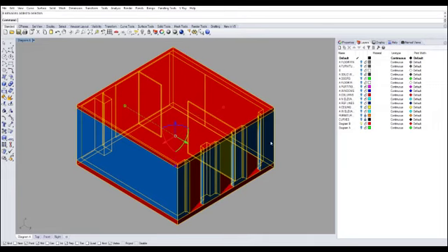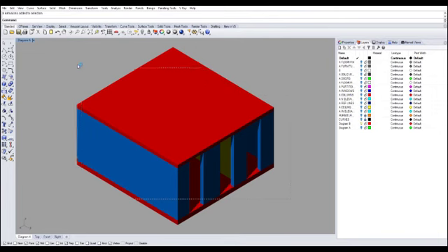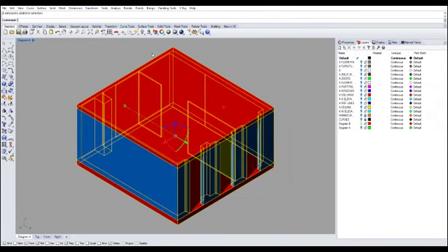Be very careful selecting and unselecting here while you're doing your layer add options. So once again, select your model, control C, copy, control V, paste it. Do not click on here. Go to new layer, type in diagram C.